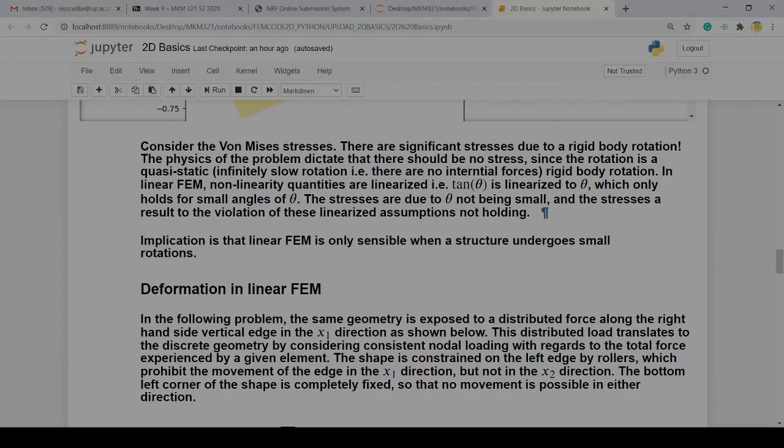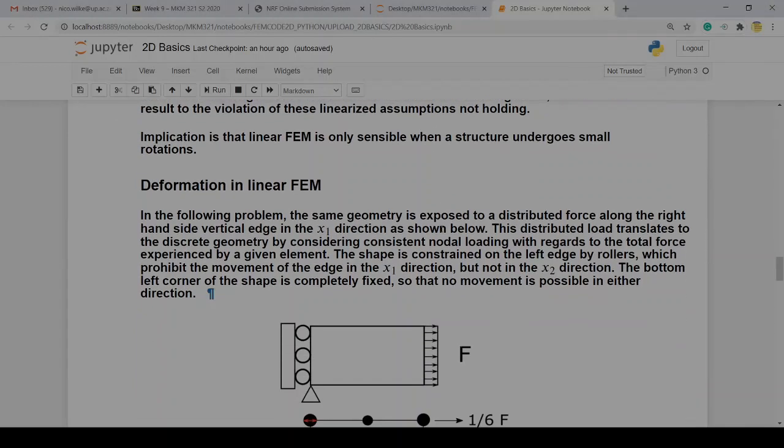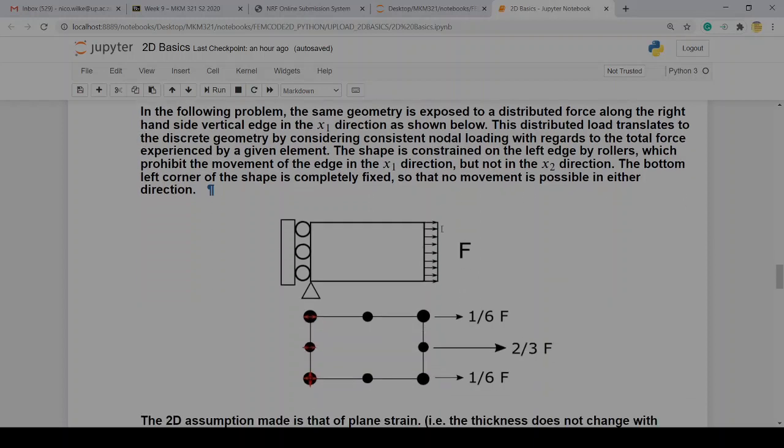All right, so next step is let's look at the deformation when we apply a uniform uniaxial tension to a little structure, 2 millimeters by 1 millimeter high, 1 millimeter thick, with roller constraints again, clamped here. So this point can't move in X and Y. These points can't move in X, only in Y. That allows for Poisson's contraction.